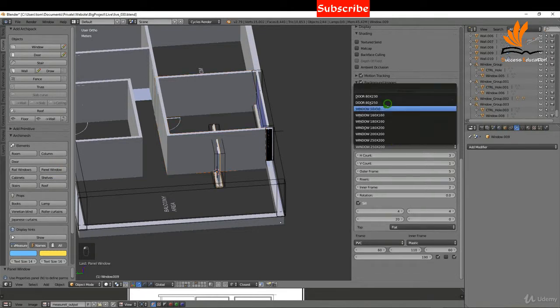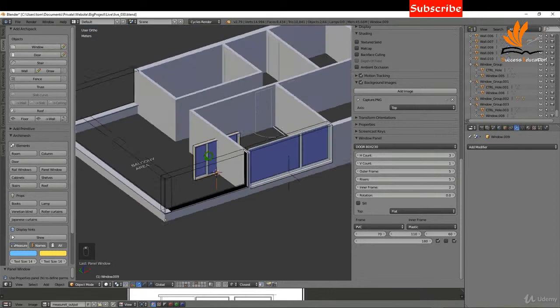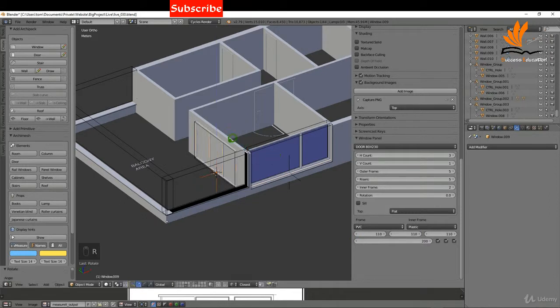Okay, I'm going to switch this then to a door, 80 by 230. And I'm going to increase the horizontal to 3, and I'm going to bring the vertical down to 1. I just want 1 panel. And for this, I'm going to set these to 110 and just check this one here. And for the height, I'm going to bring this up, I think, to 2 meters. So 200. And of course, we need to rotate this. So RZ -90. Press enter.